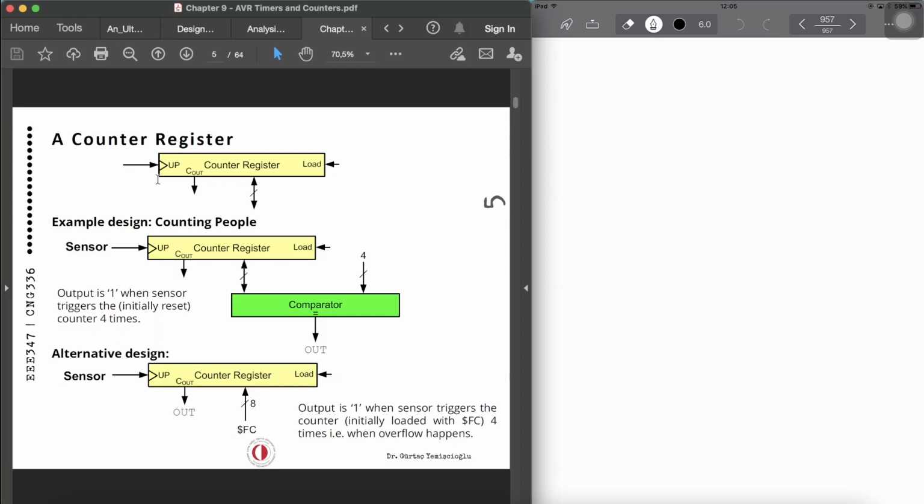So whenever something happens over here as an external source, the clock is going to tick. So in a way that the counter register, if you do remember from logic design, will start to increment. Okay, so the counter is incremented, and in this way, the content of the counter represents how many times an event has occurred actually.